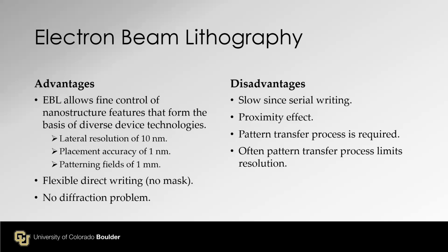Flexible direct write, no mask, wonderful. No diffraction issue. Optical lithography often hits the diffraction limit, so we cannot make something too small. That is wavelength related. The major disadvantage of EBL is that it is slow.